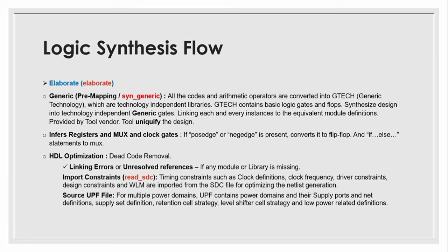Now here comes a question: can we do synthesis without timing constraints? The answer is yes, it is possible to do synthesis without giving timing constraints. However, the resulting design may not meet its timing requirements. The timing constraints are used by the synthesis tool to ensure that the design meets its timing requirements, right? Timing constraints specify the maximum delay that is allowed for each path in the design. So without timing constraints, the design may not meet its timing requirements.